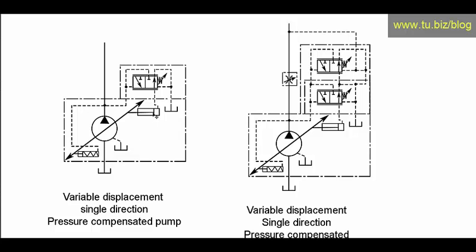It's this very same pump, but with a much more detailed drawing, in which the pressure compensator valve is right here. It's actually this unit over here, and it shows the connection on how it works inside the pump by varying the displacement and the cylinders inside the unit. And so it can de-stroke the pump and stroke it back up and do all the good stuff that it does. But it shows the more complete drawing of a pressure compensated unit.